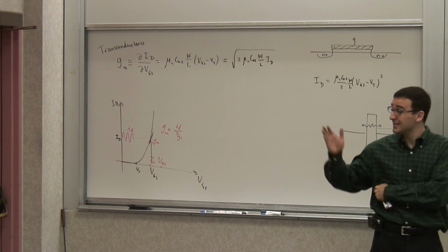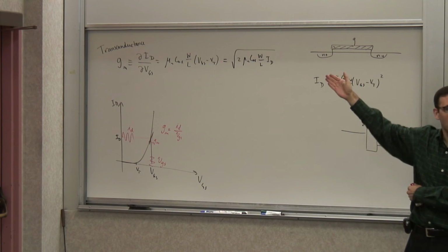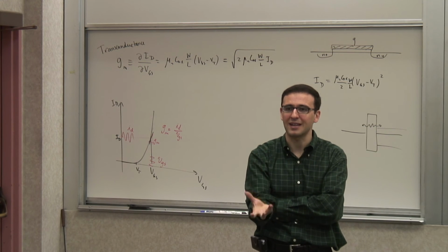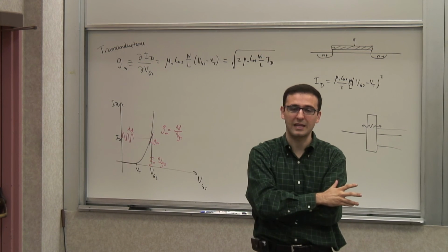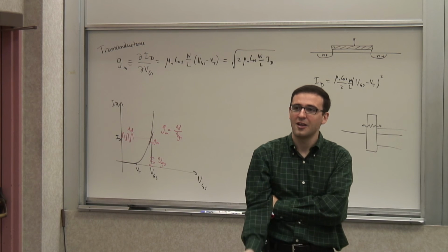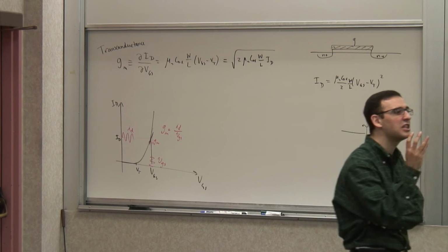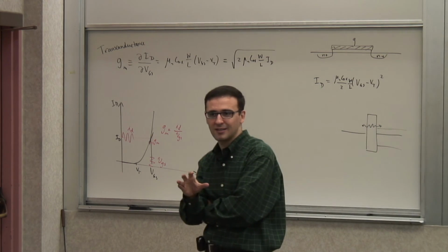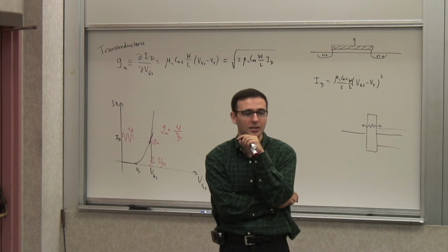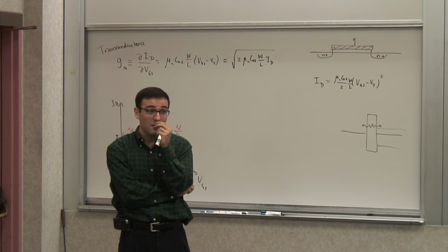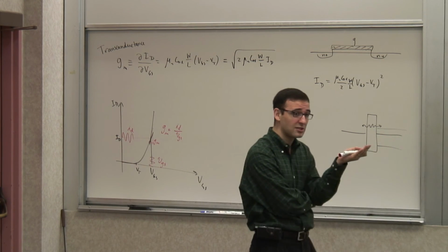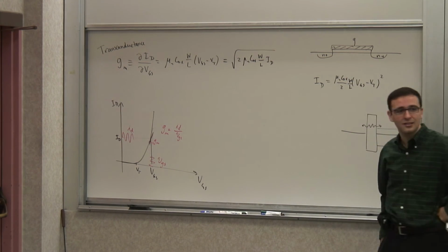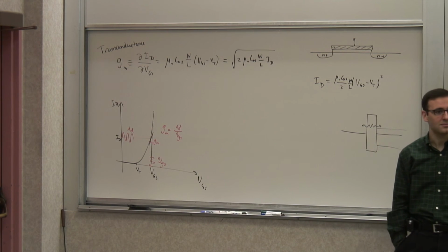And actually, this is a problem in today's microprocessor. Because microprocessors today are not limited by the number of transistors you can actually reliably make, interestingly enough, although you're making hundreds of millions of transistors. They are limited by how much power you can dissipate, how much heat you can dissipate, how you can get the heat out. So that's what limits their performance, primarily. First order, I mean, there are a lot of things, but that's the first order effect. Now, the temperature is determined by how much current you draw from the supply. So if you have to draw this extra current through the gate, then you have a problem.